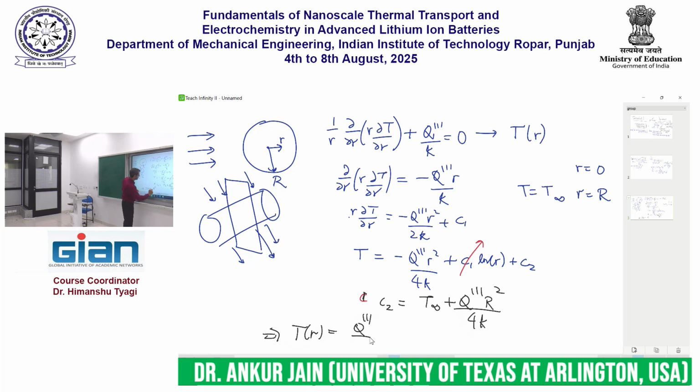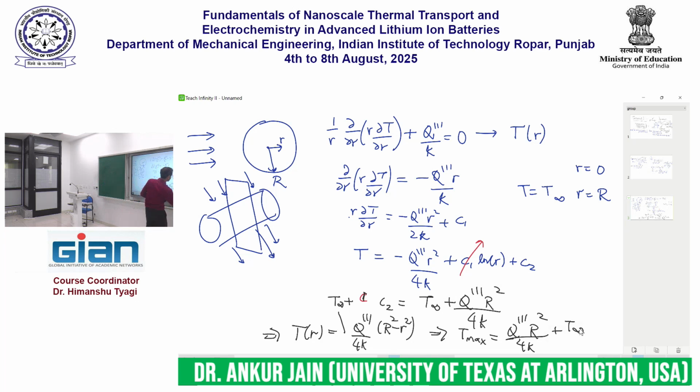which means that T as a function of r is given by q triple prime over 4k times (R squared minus r squared). Correct? And therefore, T max is equal to q triple prime R squared by 4k. This is the maximum temperature in the cell. Sorry, I forgot to add T infinity here. There should be T infinity plus that, and there should be a plus T infinity here as well.